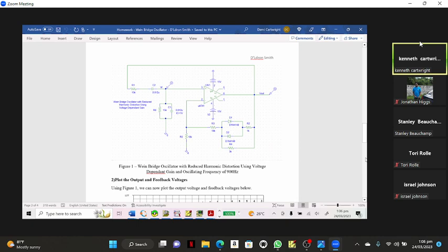You see R3, where you think RF should go, but that's not where RF should go. Where does RF go? RF goes from this output back to here. What resistor goes from here to here? Well, that's R3, and that's 3K if the diodes are off, right? You realize diodes are either on or off in a circuit, right?